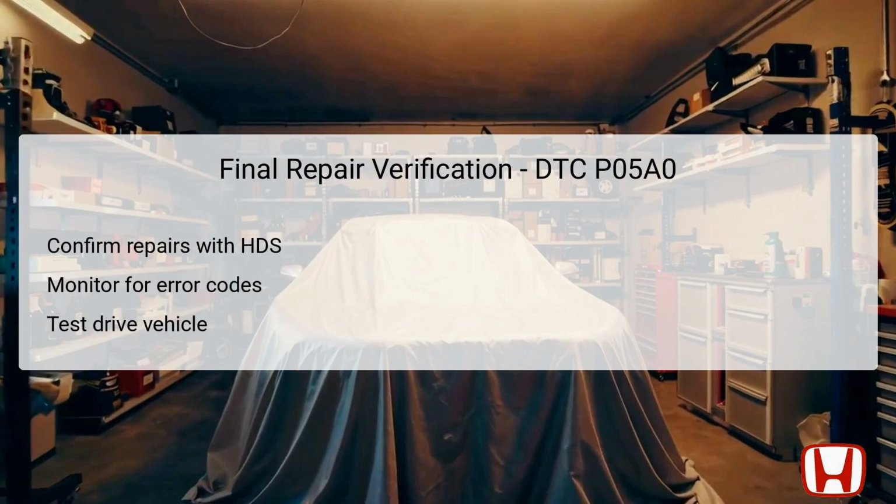After completing all troubleshooting steps and repairs, final verification is crucial. Use the Honda Diagnostic System, HDS, to confirm that the repairs have resolved the issues associated with the P05A0 code. Ensure that no error codes have returned while performing a system scan.